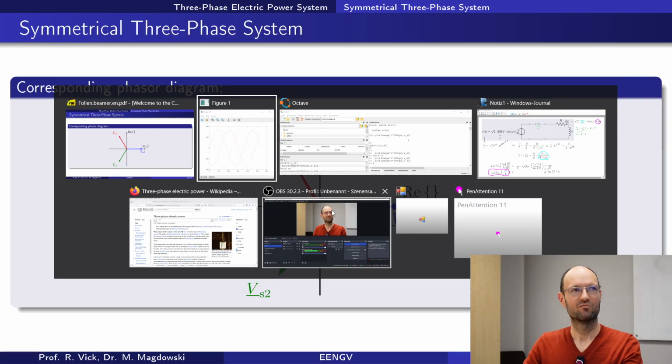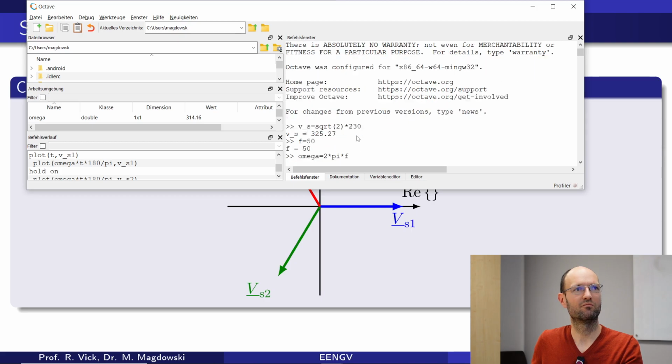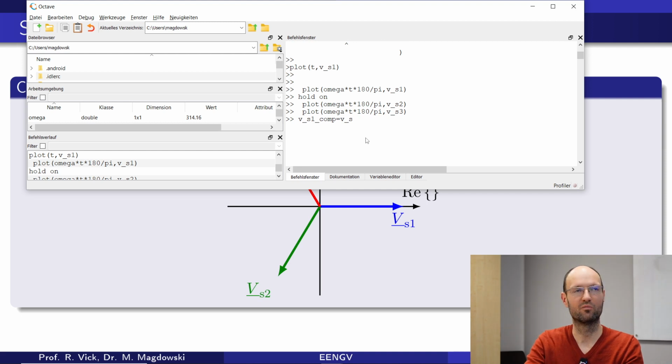We have to convert them to Cartesian form? Yeah, so at first we would need to write them as complex phasors. So here is my first source voltage. And now if I say this should be complex, then this just gets the value of my magnitude that I've chosen. So here I should get the 325. We had no separate variable for the RMS value.